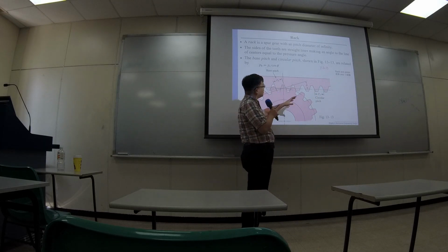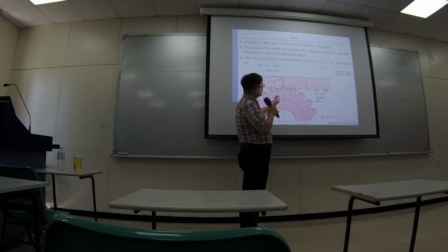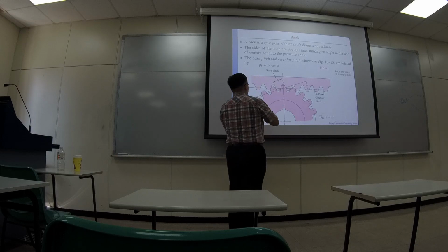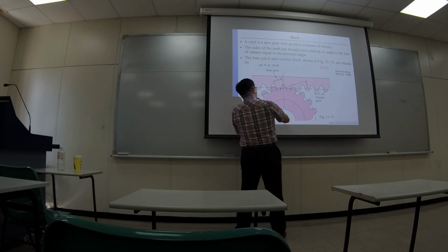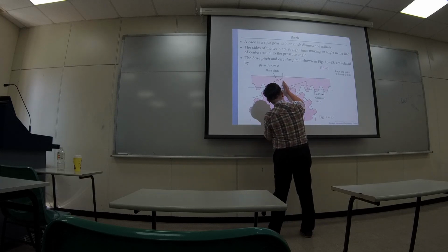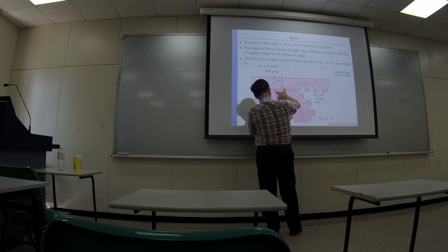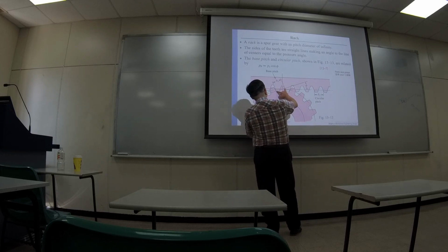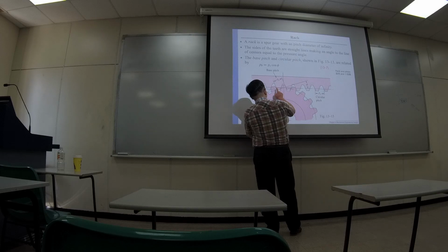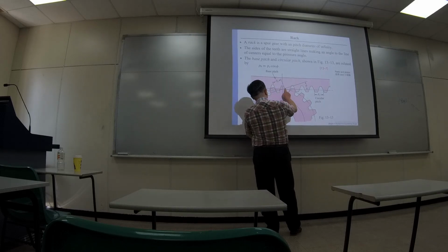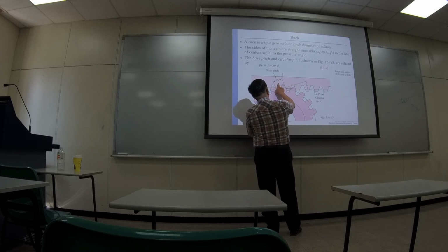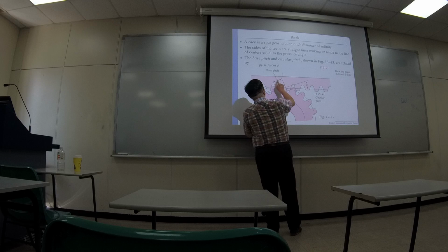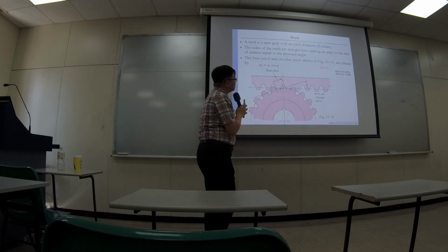But if we study the shape of the teeth, we can study in a different orientation. And over here there's a tilted line. This is basically the pressure line. If we observe the pitch along this line, then there is another way to study the distance between the first tooth and the neighboring tooth. Then there is a pitch analysis along this way, and this one is called the base pitch, okay?